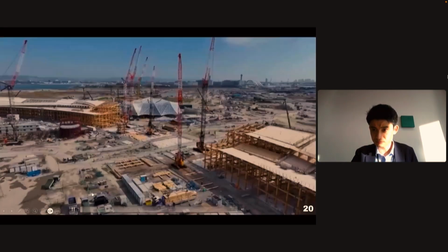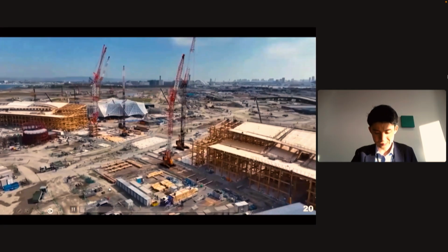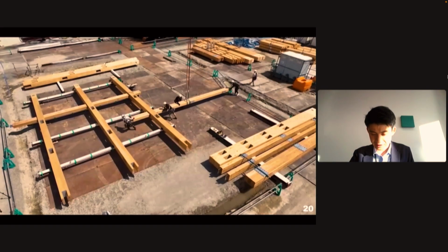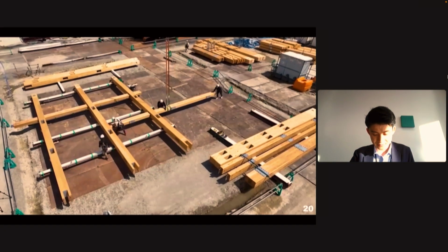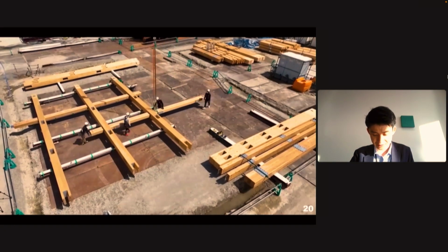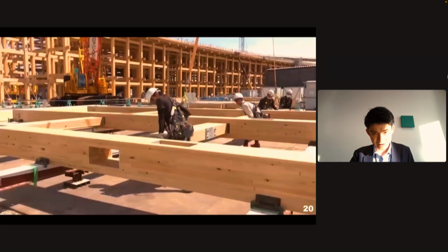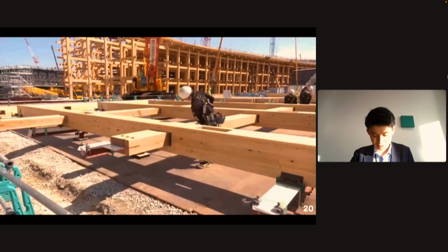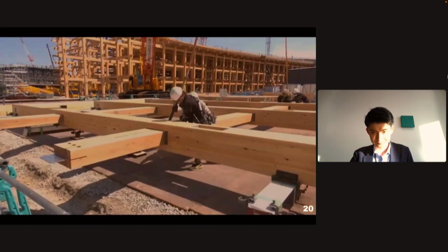So now let me show you how the ground ring was constructed. Most timber components are processed precisely in factory and delivered to site. First, we assemble planar units at ground level. We insert beams through the crowns. This is where the Nuki concept appears in the workflow.